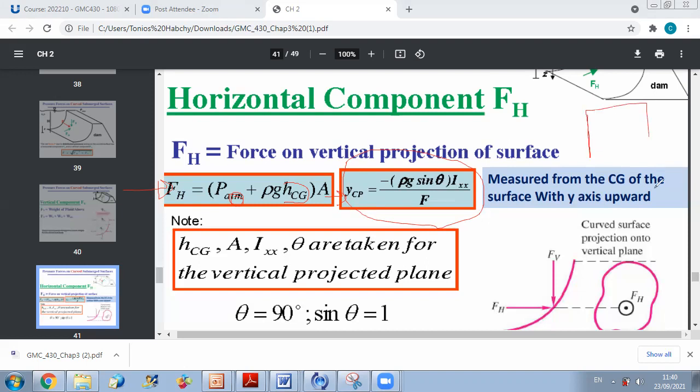If you remember, we talked about the possibility of providing a variable frame to find the position of the center of pressure. So to remind you, let's say you have this vertical surface. If you consider the origin of Y from the free surface, then we developed together that YCP is Y of C plus a certain length, which is the one we developed in the formula. Also, you have another method that considers just the distance between the centroid of the area and the center of pressure.